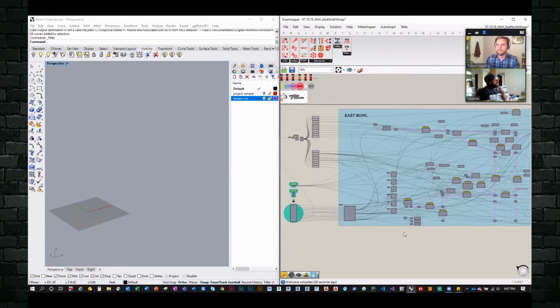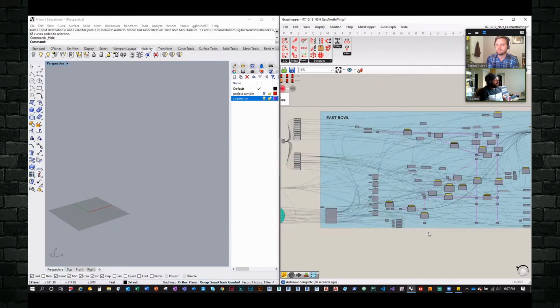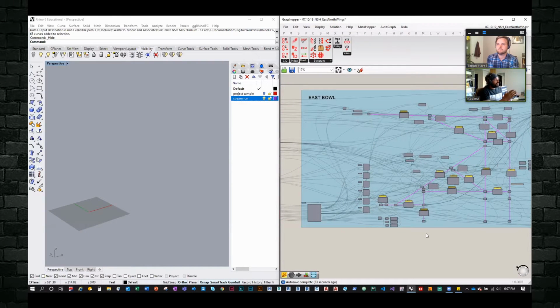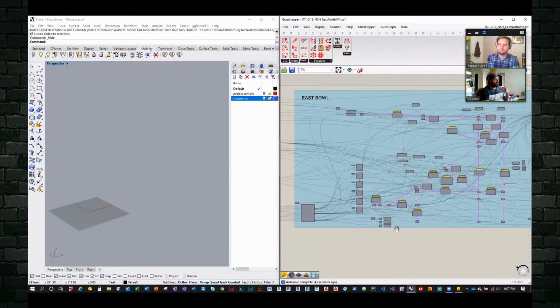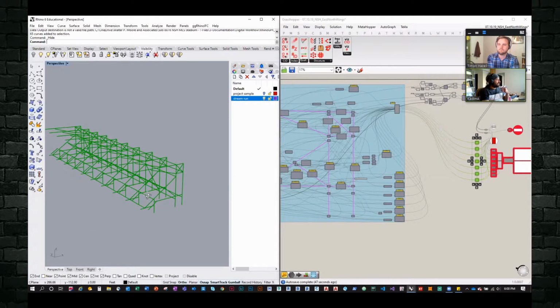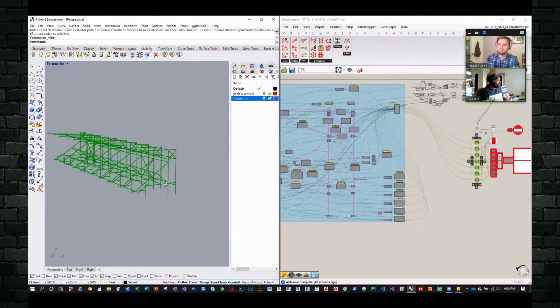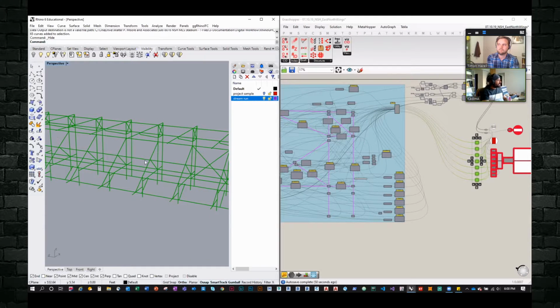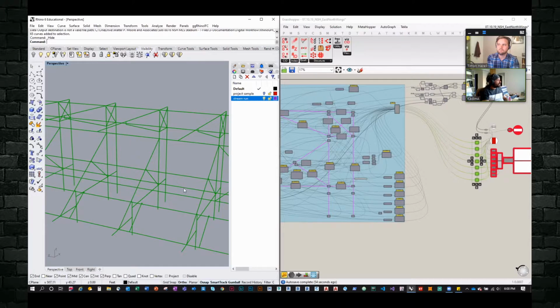Yeah, so that was actually a kind of a learning curve for me, because when I first started out, I'm very used to data flowing downstream, and this is how I troubleshooted it. But given how complex this script is, there are just so many components to it, it was easier for me to troubleshoot. Like right when I select all these nodes, I get the preview in my Rhino window. If there are some lines that are connected incorrectly, I know right away. So let's just say that there's some random member connected to this corner.